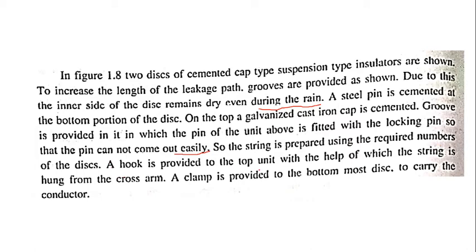A hook is provided on the top of it, with the help of which the string is hung from the cross arm. A clamp is provided at the bottom of the disc to carry the conductor. So let's see the figure first.